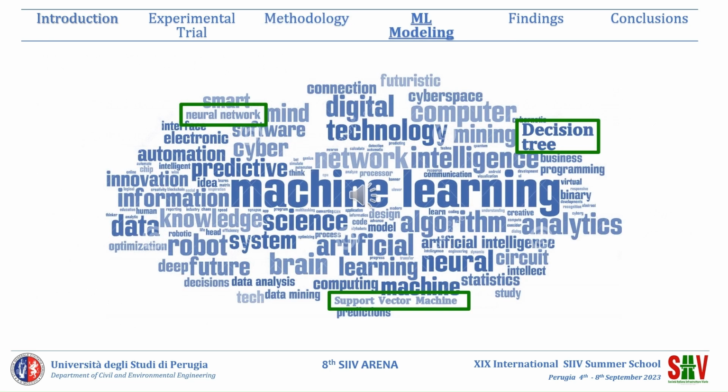Machine learning approaches were used to model the mechanical behavior of the investigated mixtures in terms of dynamic modulus and phase angle, on the basis of the same input features implemented in the empirical equations just observed, plus a categorical variable distinguishing the aggregate nature. This is a problem of machine learning regression, and consists in finding a function that approximates mapping from an input domain to real numbers based on a training sample. 3 of the most common algorithms to accomplish this task are support vector machines, artificial neural networks, and decision trees.